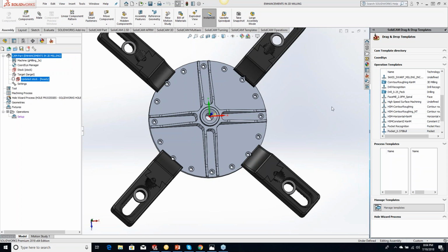So with that, one of the major things that we did with the 2.5D is the fixture protection. So you'll see right here we have a part. I'm holding it down with 4 toe clamps. Well, obviously I don't want to hold this part down with 4 toe clamps all at once because I won't be able to machine everything.